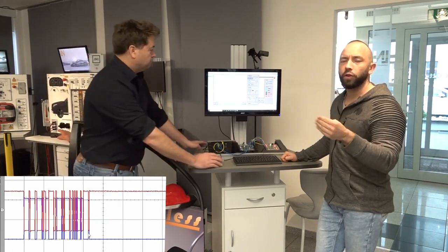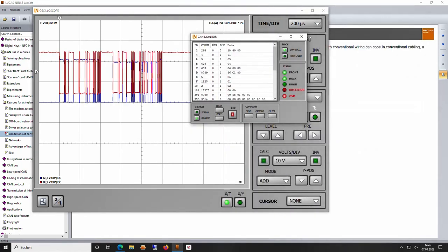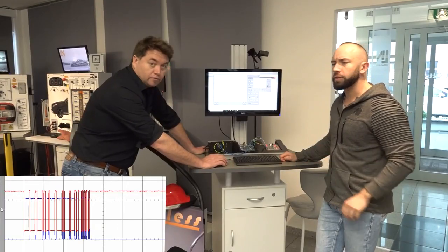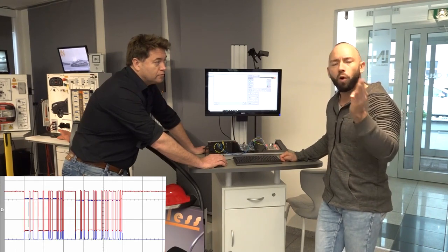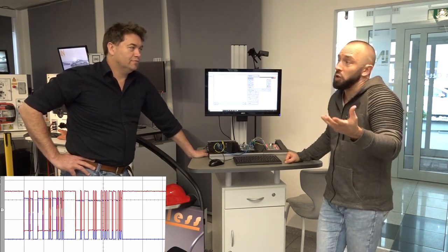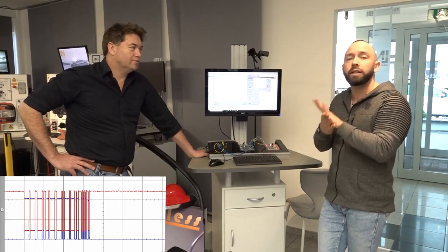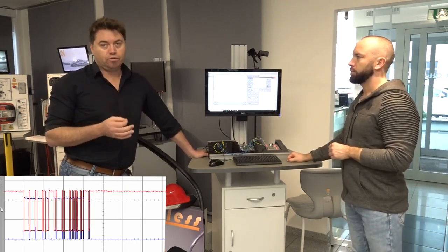And that's why you use that, for example, in comfort systems, because they are not safety relevant, but it would be really annoying when one cable is broken and, for example, you can't use the seat adjustment anymore. So then you have to go to the workshop much more often. Even when one cable is broken, for example after 10 years, you still use the system, and from an outside perspective everything's completely okay, and basically there's no need to go to the workshop. Of course, you will have a DTC in the fault memory, but for the driver, you won't have basically any negative aspects there.